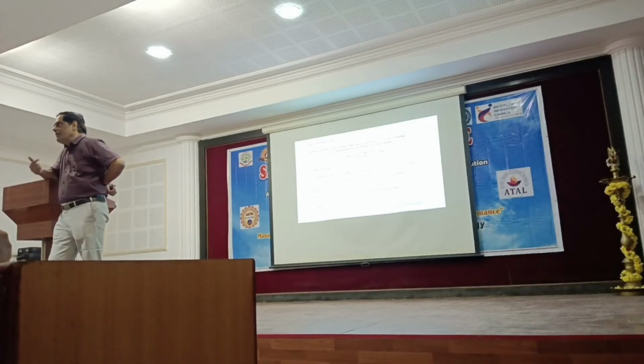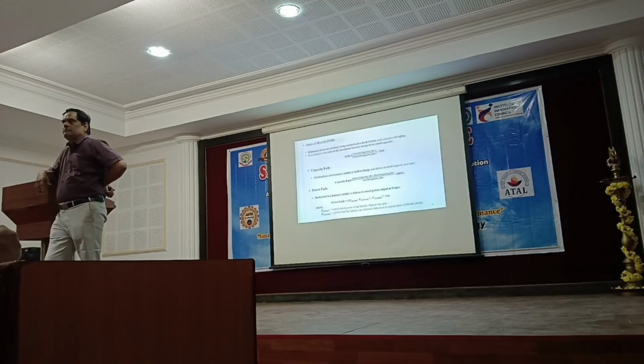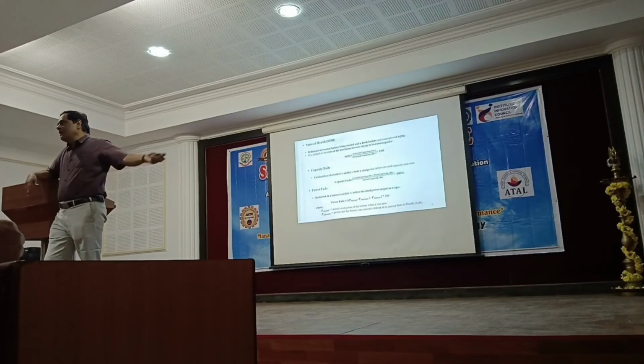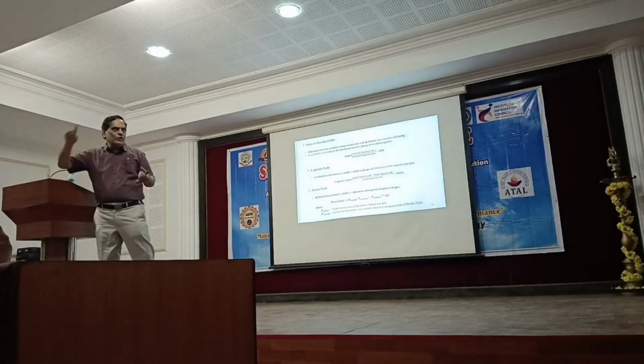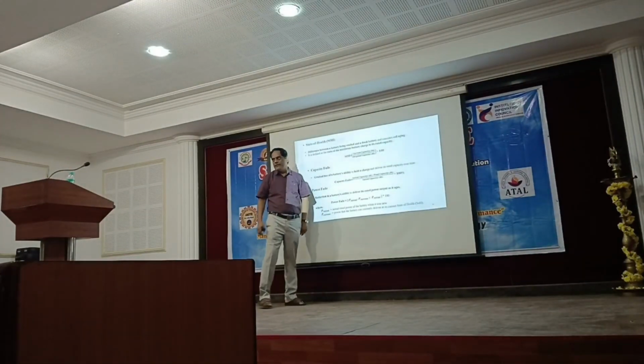function of time, when you use the battery for a large number of cycles, we are looking at aging. What is the current health of the battery? Fresh battery and old battery, used battery. For SOH estimation, I should know SOC also. SOC should be known as a function of time, how many cycles I used it. If you account for that, I know state of health actually. Having known state of charge and state of health, I can determine capacity fade actually.